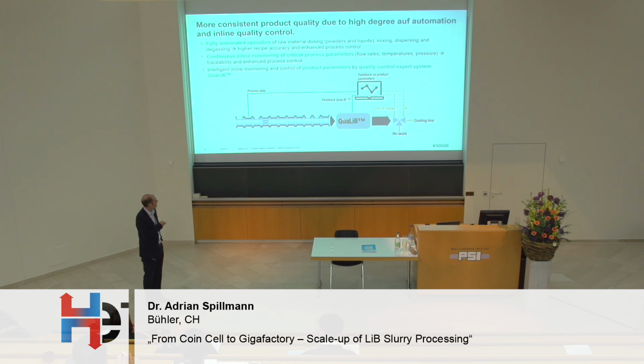Basically, this system allows to inline measure the quality of the electrode slurry which is coming out of the mixer here. So these are basically parameters such as the viscosity. This is very important for the coating step, but also solid content, particle size distribution, and so on.